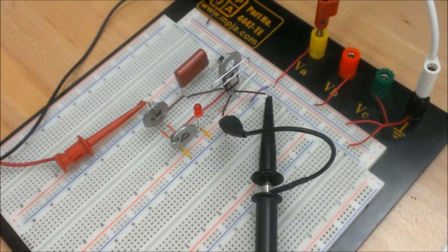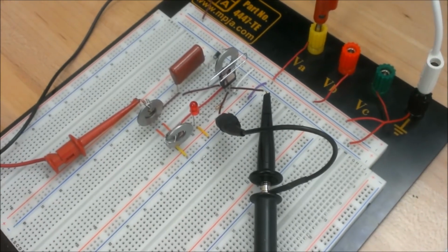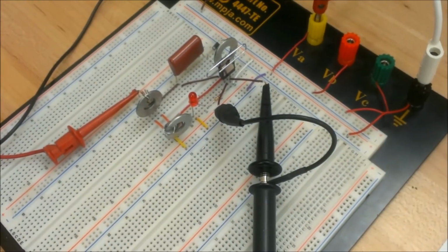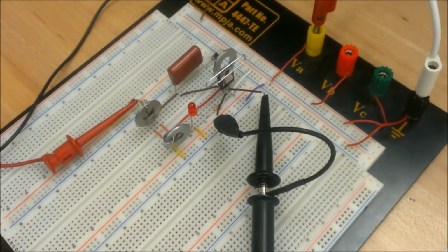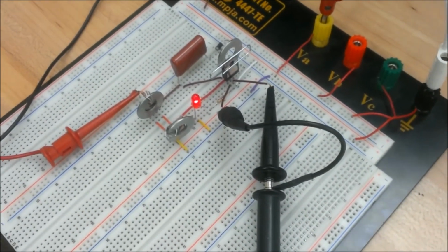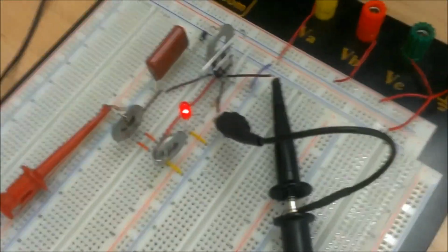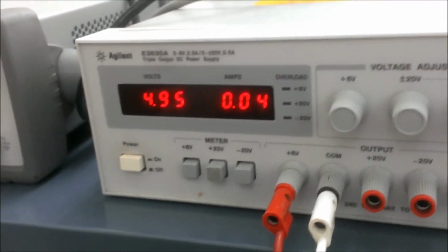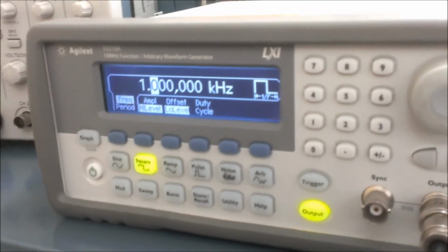Okay, we're back again with the bootstrap capacitor high side gate driver to get some action shots with the square wave, because before we only saw DC. So we're going to turn on the output and the power supply. The LED comes on and the oscilloscope comes on. First, as you can see, the MOSFET is still powered by DC voltage, but then we have the function generator hitting the signal, which used to be the V2 voltage.